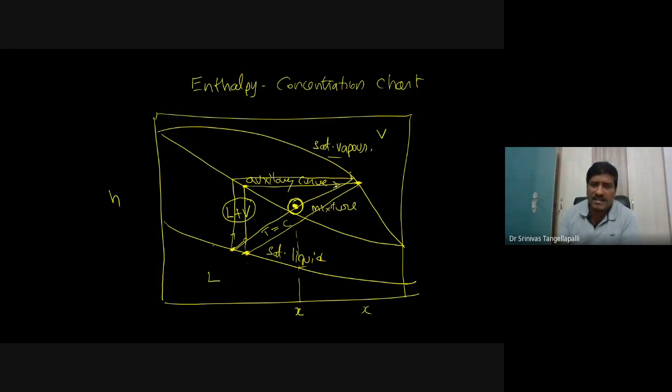That means this line is passing through the state. What I can see, my results are showing this is the final temperature. At a given pressure and concentration, this is the state we are able to show, and this is the temperature. The temperature is the result of this iteration process, and this is the resulting liquid concentration, and this is the resulting vapor concentration. So by supporting this auxiliary curve, it is easy to solve the mixture properties using the iteration method.